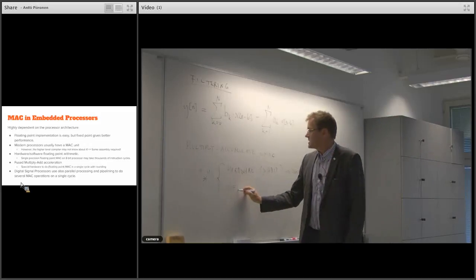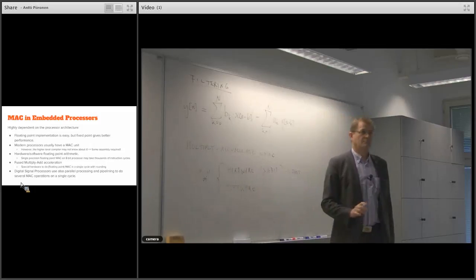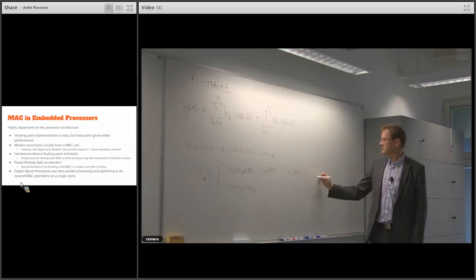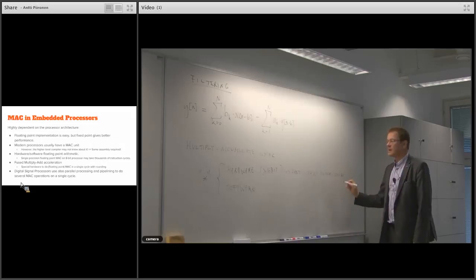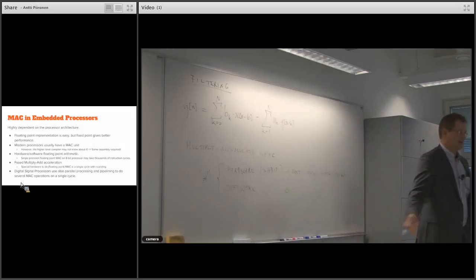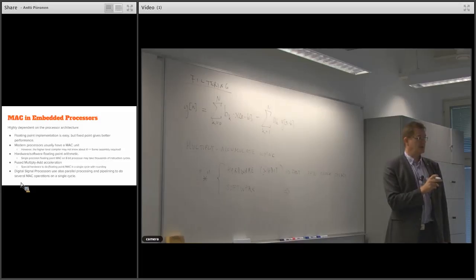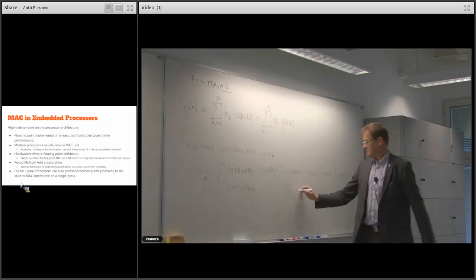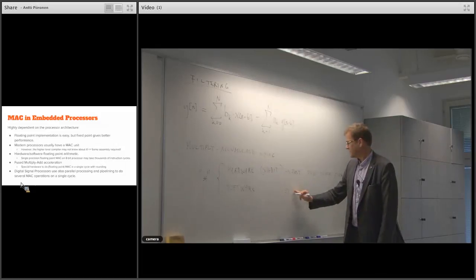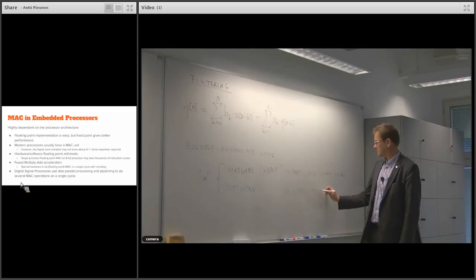But anyways, you can always do it by software. While hardware is usually just, say, a few clock cycles, if you do it by software, of course, even with an 8-bit processor, you can do floating point arithmetic if you have time to do it. Single precision floating point multiplication of two numbers generally takes about 200 instructions. And each instruction is 5 to 11 clock cycles. So we can say this is slow, sluggish, thousands of clock cycles.